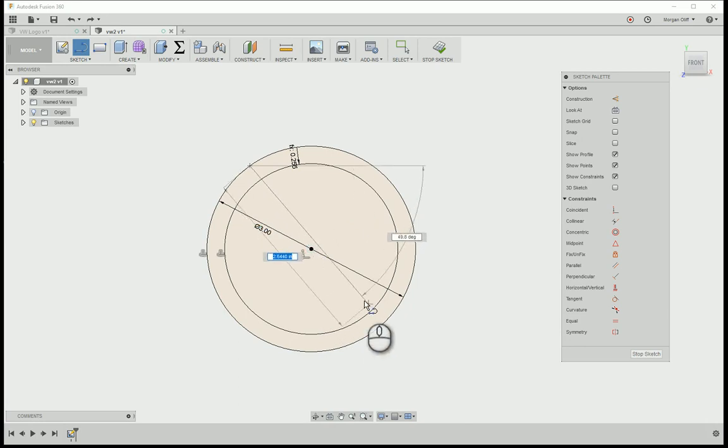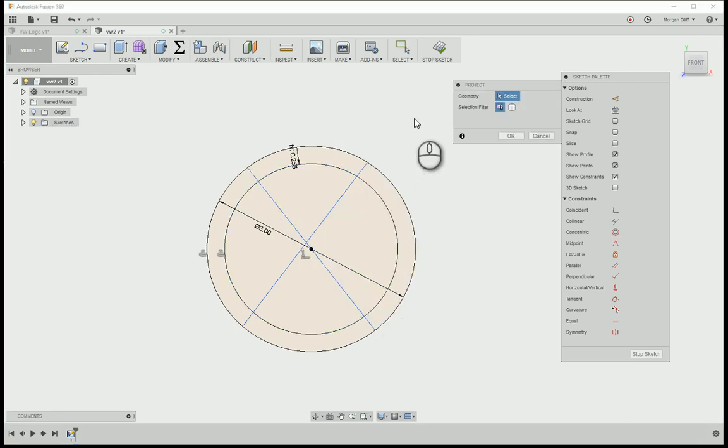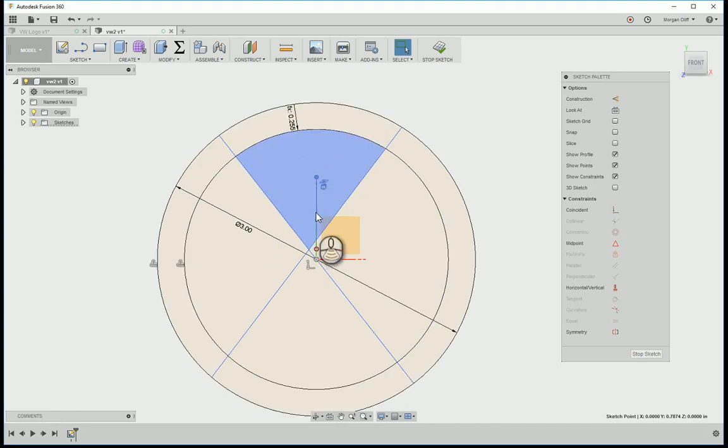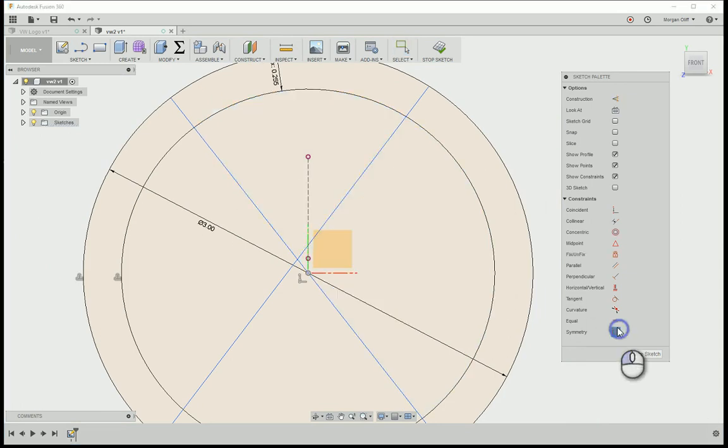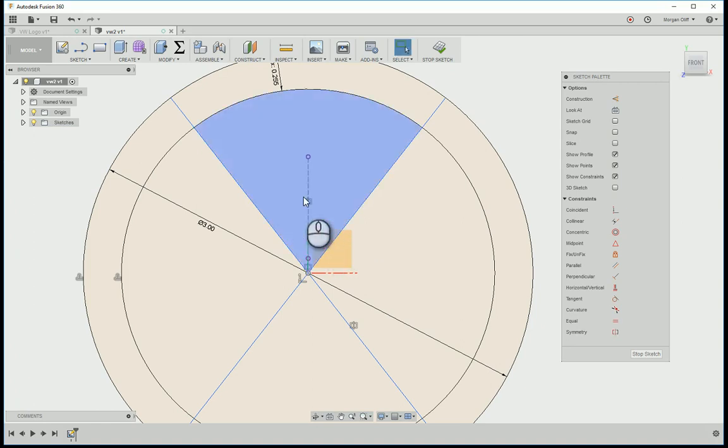They cross the center point there, and it's not wanting to snap. That's not a problem. All I want to do is snap it from each side, and then constrain this coincident to here. Oh, and here's my favorite trick. If I want a center line to create a mirror constraint around, I pop open the origin and just grab whichever axis is vertical or horizontal respectively. Go ahead and convert that to projected geometry, convert that to sketch geometry, and then I'll pick a symmetry constraint between this, that, and we have full control.